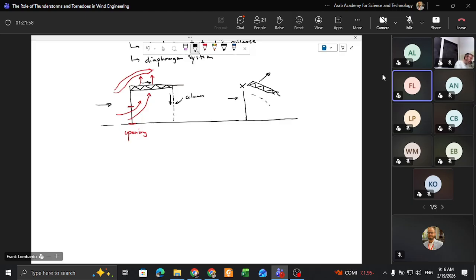And then you end up with collapse. There's really nothing holding it there. And honestly, we've seen some damages in the US where the wall isn't even anchored into the ground at all. It's just sort of sitting there. And I'll show some examples of that. They call that tilt-up construction.